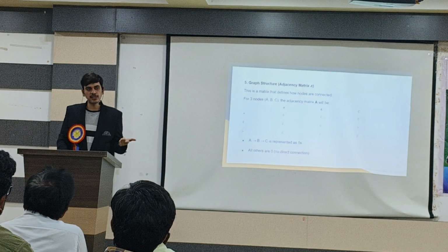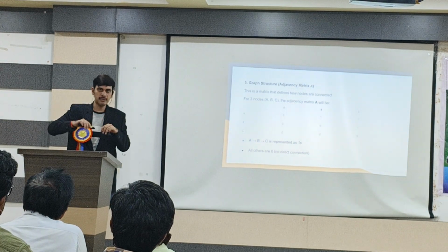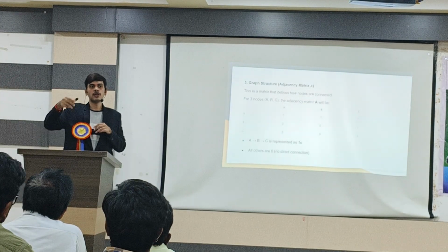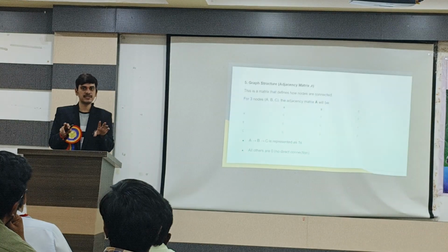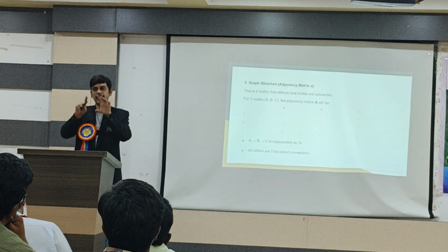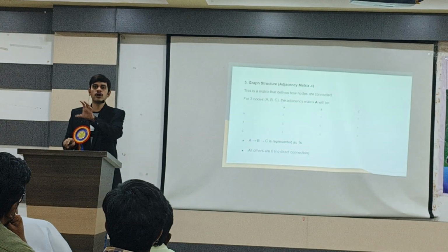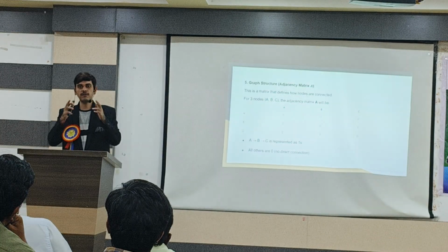But at every stage of the project there is this feedback loop: we give the netlist, we analyze the timing, and we give feedback to PnR. PnR means place and route. They place the cells, and there are 2 types of placement. One is the SoC level. An SoC has, for example, 10 blocks: an audio block, a modulation block, a video processing block. At the top level they do the floor plan.